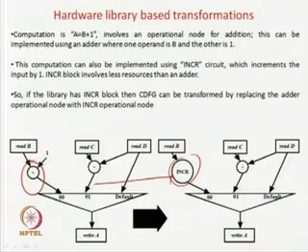Incrementing the value by 1 is sometimes also required in computing 2's complement and so forth. Many times you have to add only 1 to a number, and in that case this is called an incrementer. So if your design library has an incrementer, do not put a full adder here, just put an incrementer and your circuit will be smaller. This transformation is possible if and only if you have an incrementer in your library. This betterment in your design is possible based on hardware available in your library, so they are called library based transformations.